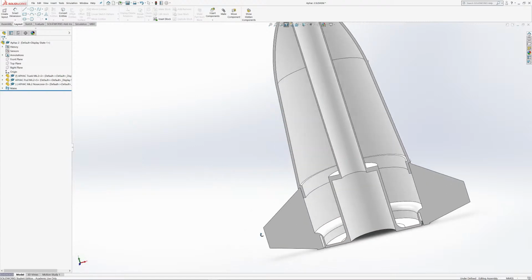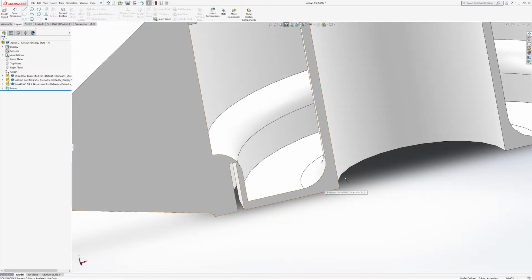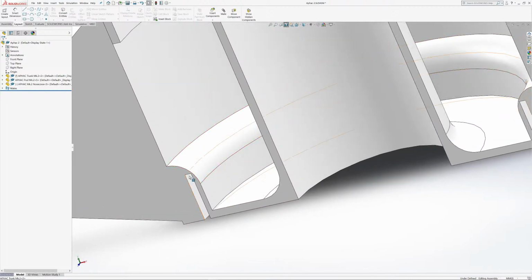It adds structural strength, and instead of just having a sheer corner here that it can break, especially when 3D printed in the way we 3D print it, this will absorb a lot of the force going into it, and it will add strength at this right angle weak point. The same goes for over here.